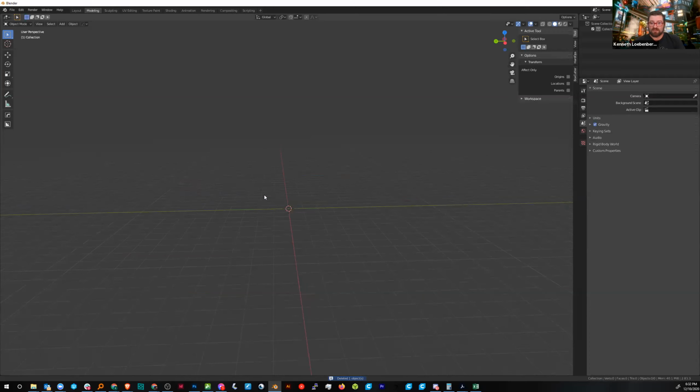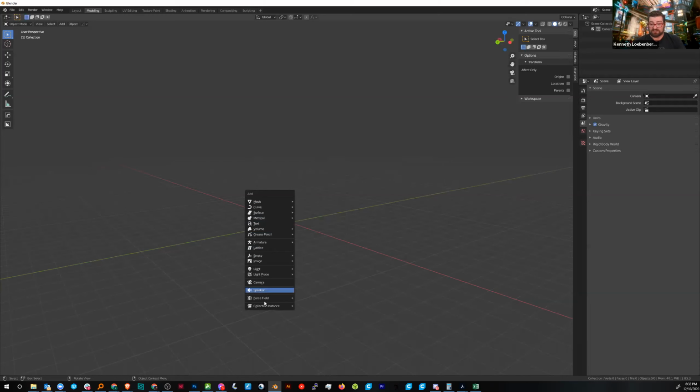So right now we have this nice gray plane. There's nothing here. Let's add a shape. To do that, we're going to go ahead and hit Shift A, and we get all these options here. What we really want are meshes, but as you see here, we have armatures if you're actually going to be animating. We can actually create empty things. So if you want something to rotate around a certain object, you can create an empty shape for your animation for later. You can drop images in as planes to use as reference. You can add lighting once you get done and add cameras. And if you're doing a movie in here, which I guess you could do, you could add speakers.